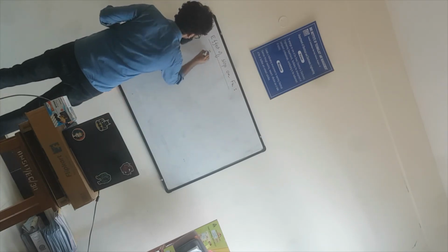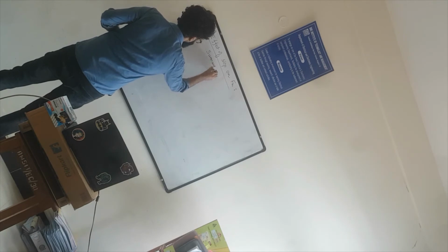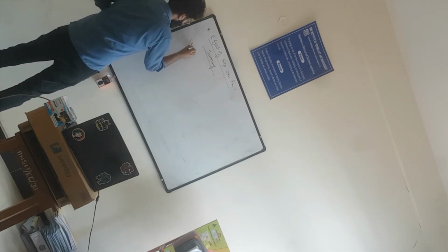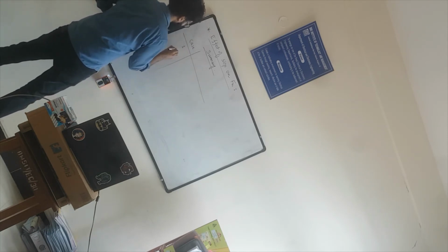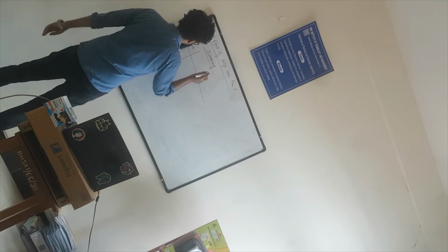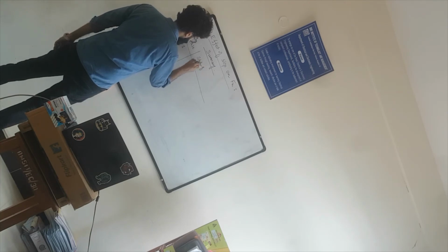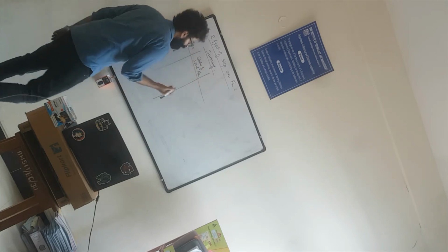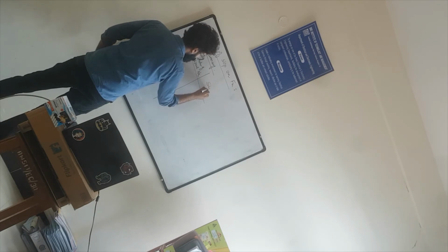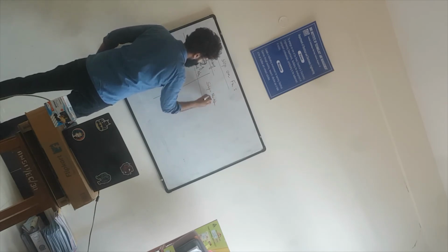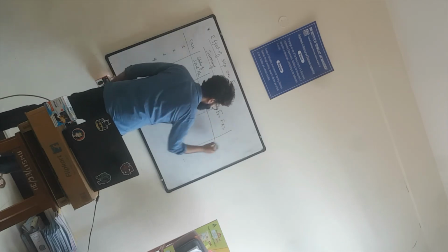So as a summary, what we can do is write a table with case number 1, 2, 3, 4, and mention the status of speed NR, and then we can talk about slip, that is (Ns minus Nr) divided by Ns, and here you can write Fr equal to F into S, and here you can write comments.